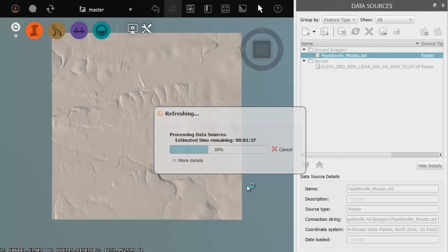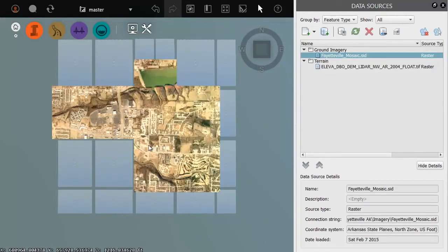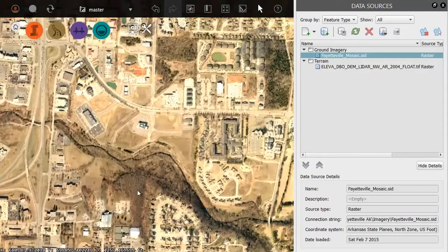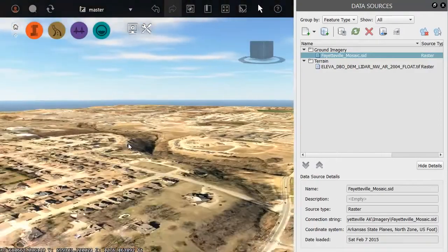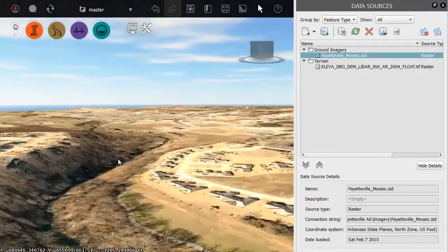We can also bring in SketchUp content. If there are signature buildings in your area, you can extract those from the Trimble warehouse. We can drop those models or any of that 3D content into InfraWorks. We can bring in SDF, that's an Autodesk GIS format. We can bring in DGN files. We can bring in DWG as well. We can bring content directly from applications like Civil 3D or 3ds Max or Revit. Now that my aerial photo is here, let me zoom in. And as I orbit this around, we can see how that photo is mapped nicely on the terrain.